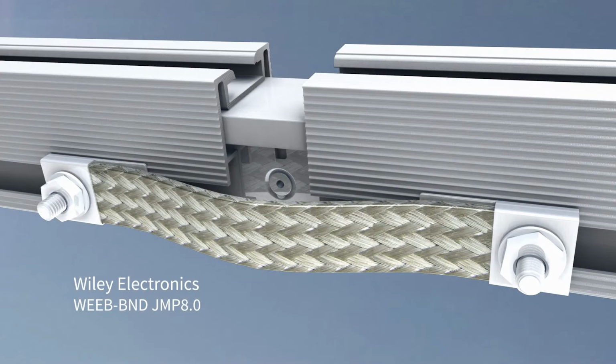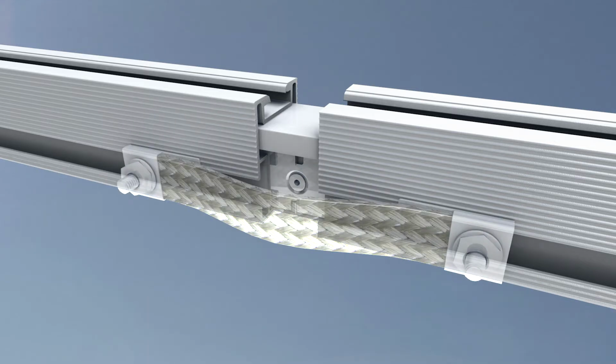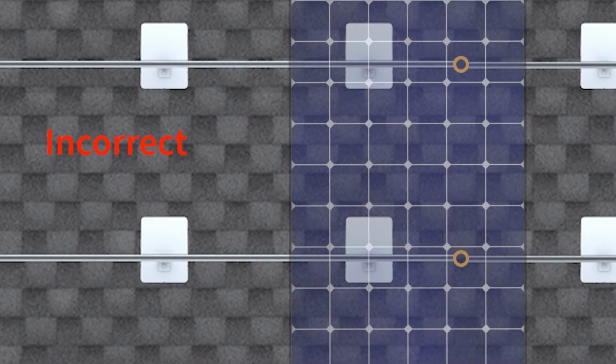In cases where a thermal break is necessary, it is recommended to use the splices in conjunction with a braided bonding jumper to ensure continuous bonding across the thermal break. After installing the rails, insert an internal splice, leaving a 3/4 inch gap between the rails. Install the bonding jumper across the gap with T-bolts and torque both sides to 16 foot-pounds. Never install modules over the thermal break.